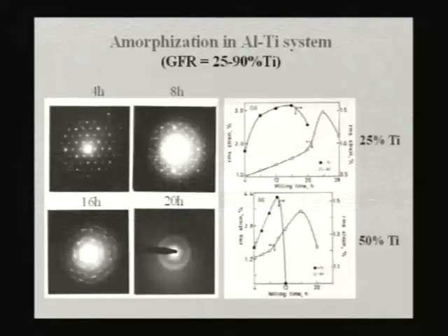So we start with today's class, and the objective of this particular part of the work is to look at the advanced aluminum alloys, particularly those with high strength. So when we look at high strength alloys, most of the high strength aluminum alloys are basically nothing but those nanocrystalline alloys or nano-quasicrystalline alloys or amorphous alloys or composites of all these.